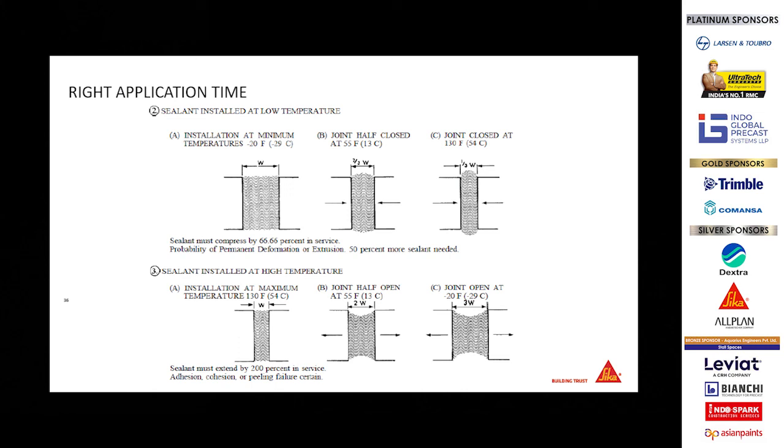Another scenario: if the sealant is installed at high temperature, the gap would be minimum. Let us assume that is W. And when the temperature drops, the gap becomes 2W.